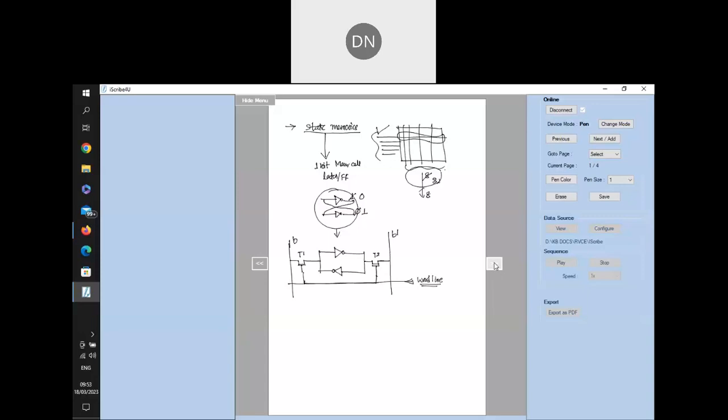Now, how does a transistor work? Whenever the transistor is supplied with a logic 1, the transistor acts like a short. That means the gate which is open gets connected here. Then whatever data is present at the output of these inverters will be available at the B and the B bar pins. Whenever you supply 0 to this, the transistor gets open. Then whatever data is present in the bistable latch will be held, because the power is there. This is the principle of how it is connected.